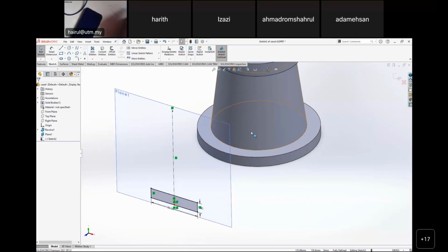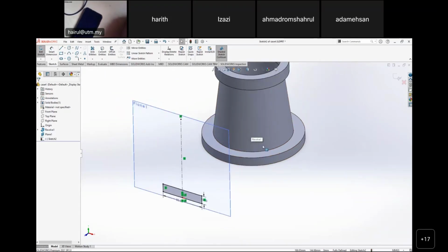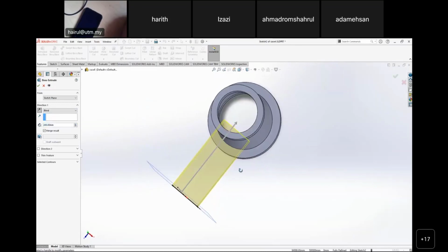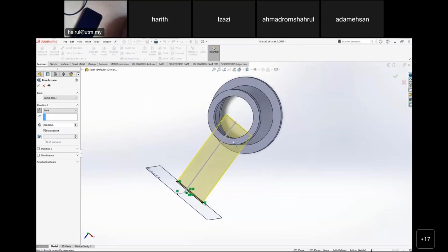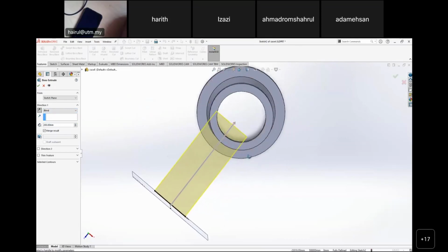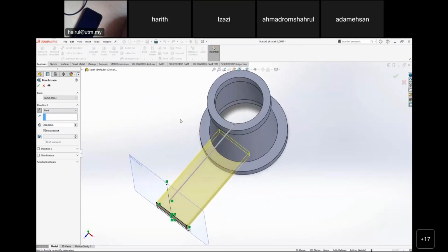To surface, but now extrude to body. Okay. What's another option? Features, extrude boss base. This one. The direction is here. Make sure direction goes to reverse. We do not extrude by giving distance. If you give distance, let's say why not we just give distance? It's possible. But if I give distance, let's say about 200, what happened? It doesn't stop like that, class. Can you see? It doesn't stop. It has excess like this. This is why, because if you use blind, it has excess here. We want it to stop.